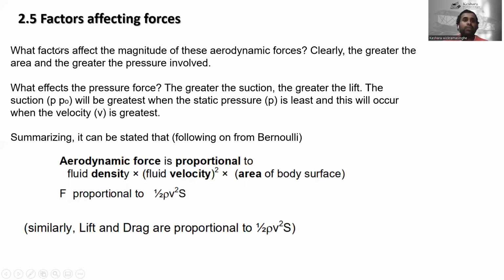All right. So now the factors affecting forces. What factors affect the magnitude of these aerodynamic forces? Clearly, the greater the area and the greater the pressure involved. What affects the pressure force? The greater the suction, the greater the lift. The suction P minus P0 will be greater when the static pressure is least, and this will occur when the velocity V is greatest. Summarizing, it can be stated, following Bernoulli,